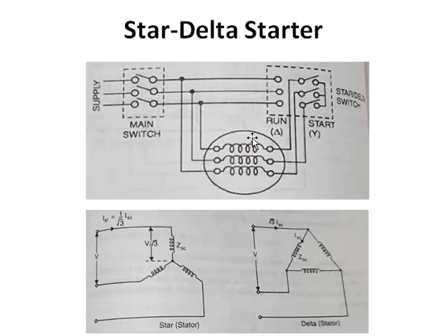points. And here is the stator winding, and you can see one end of these is connected to this side, and this is the switch. This is called a star delta switch. Star delta switch means it can put the winding in either star or delta. We have a total of 6 terminals.